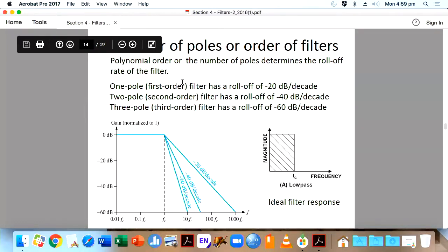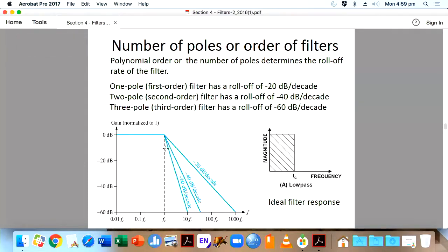Active filter, the beginning is second order. I will come to that point. Then for DSO, it's up to you whether you want 2-pole, 3-pole. With 2-pole, you are getting minus 40 dB per decade, minus 60 dB per decade if you are using 3-pole. So you have to keep in mind the space, because the board size is fixed. You can't have more size.